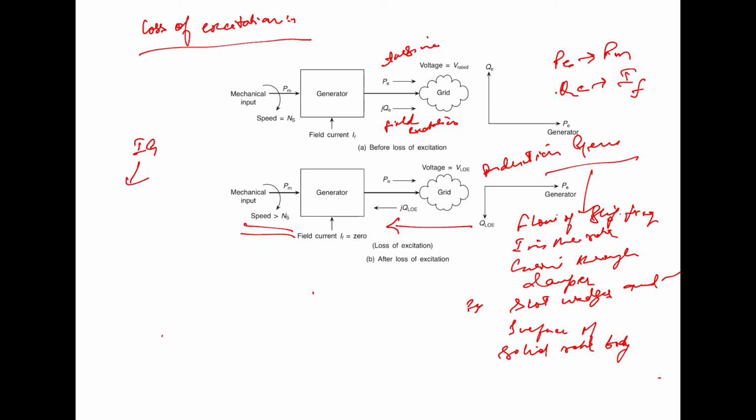and there is no risk to the instability of the system. However, as you know, the generator is not designed as an induction machine, so abnormal heating of the rotor and overloading of the stator winding will take place.